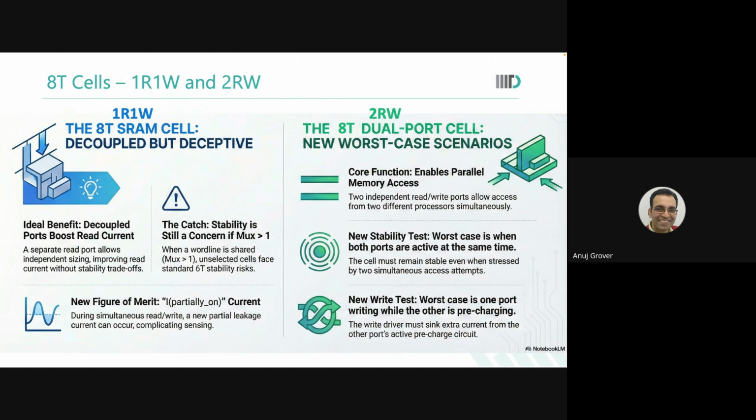In the memory, the bit cell has random data stored, so how will we know, to avoid coupling, which one to select and which one to keep discharged? So you cannot design it like that. You have to design in such a way that you are able to emulate the worst case coupling, and ensure that even in the presence of that worst case coupling, your circuit works. There's no failure. You have to leave that kind of margin in your design.